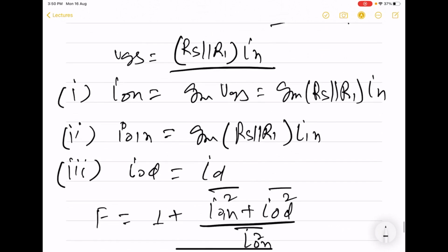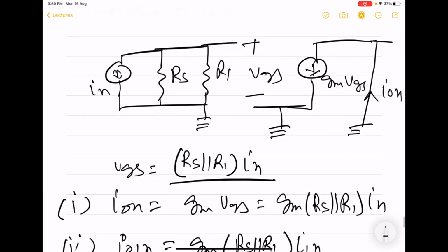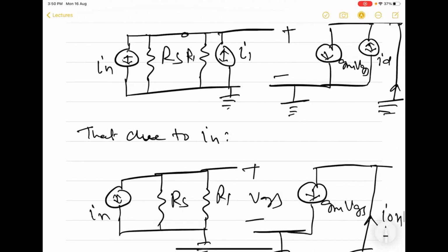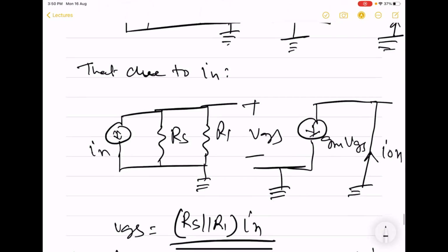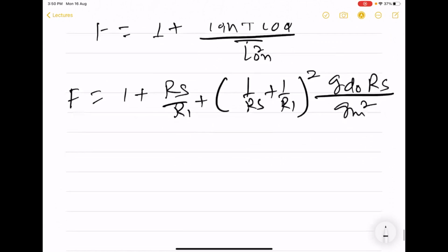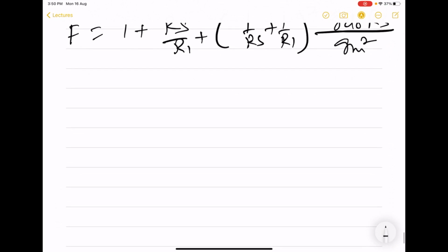So this model will be useful when we have a larger number of parallel components. Here we had only 2 components, so we were able to easily handle this circuit even with the voltage source model of resistors. However, as an exercise, if you want to include the gate to source capacitor, keep in mind that once you include it, the input impedance is no longer going to be 50 ohms.